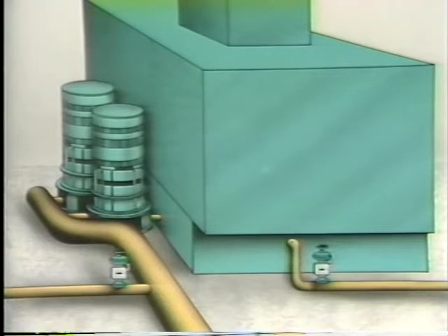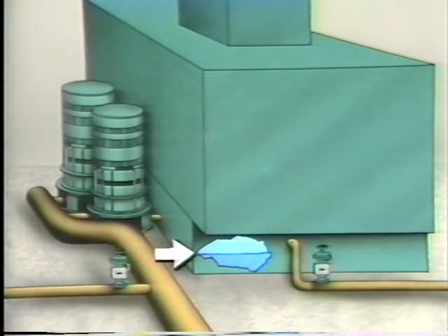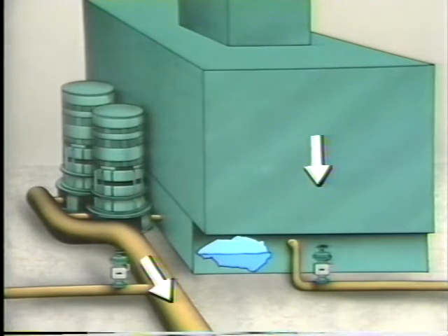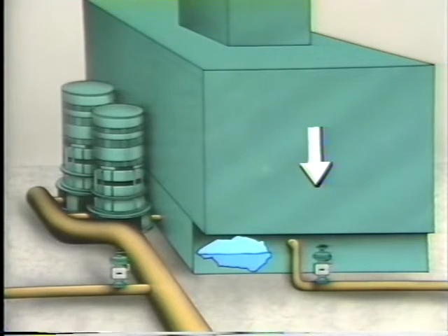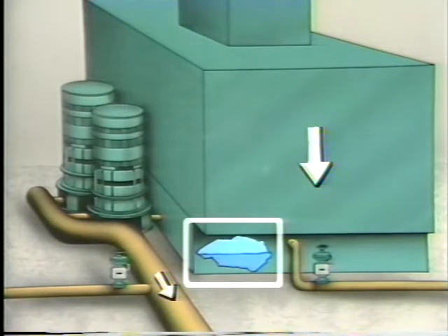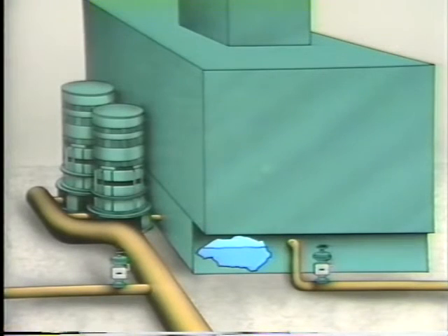Now, in this system, the variable that has to be maintained is water level in the hot well. If the amount of water entering the hot well is balanced with the demand for water from the hot well, the level in the hot well will not change. But if the amount of water entering the hot well is greater than the demand, the level in the hot well will gradually increase. When the level rises to a predetermined point, a valve starts to open in this pipe called the draw-off line to drain off the excess water and keep the level from rising any further.